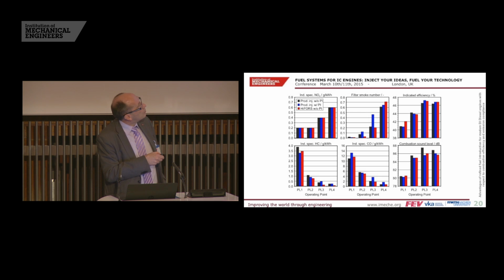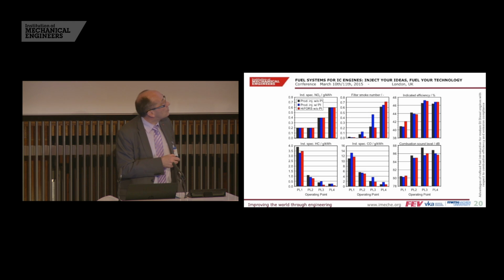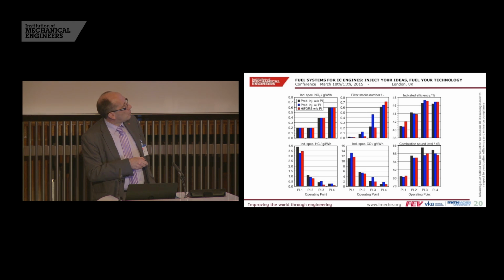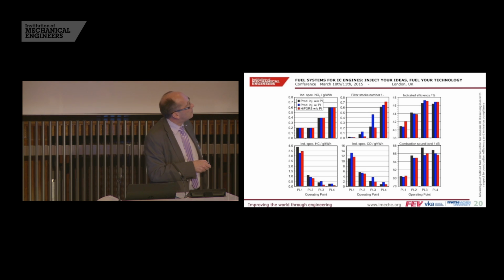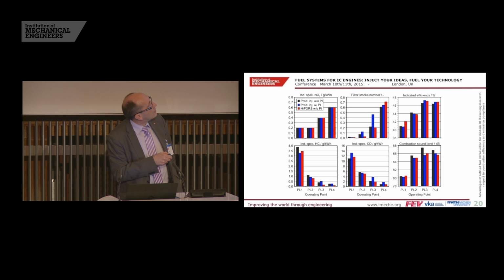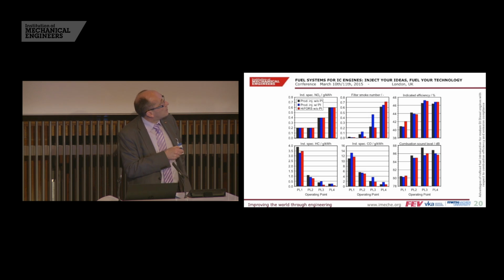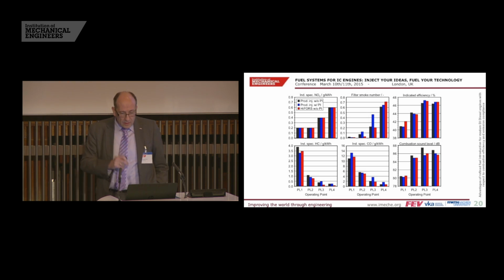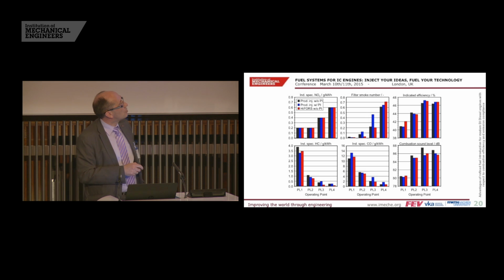In the light load operational points, we often have significant smoke benefits. The calibration was intended to be at least similar or better in terms of NVH, so this was one dominating parameter. And then we have the results later on. See here, for example, at the highest load point, there's a slightly increased smoke emission, but significantly lower noise behavior.